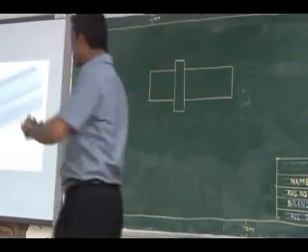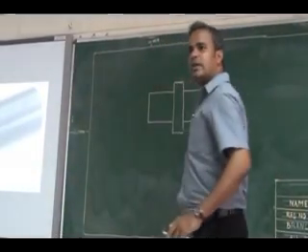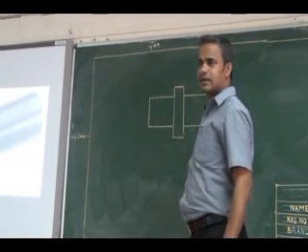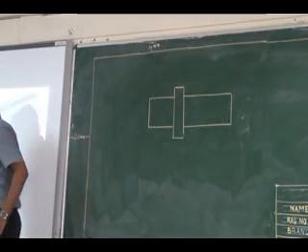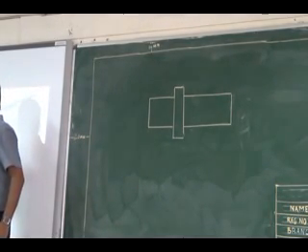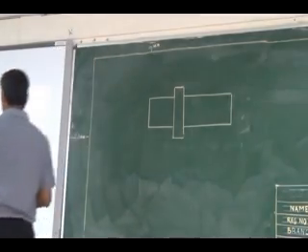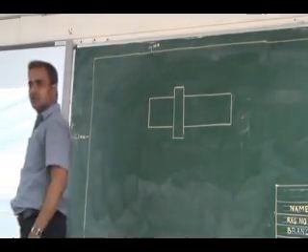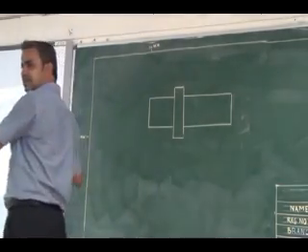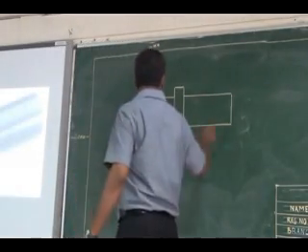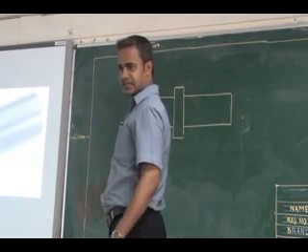This is a visible outline I can see. Forget about the hole for now; it is just a shaft. It is a hollow shaft, so whatever depth it is hollow is not visible. If I look at it in this orientation, I can see the front view like this. Whatever visible edges I can see are drawn in the continuous thick line.